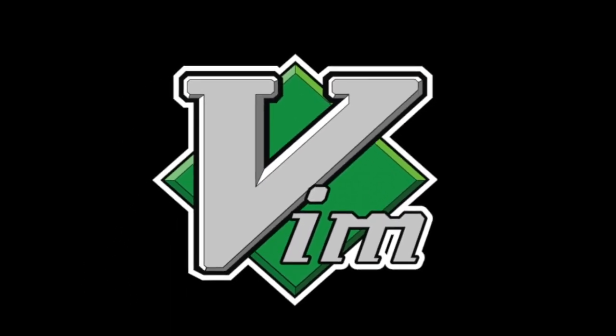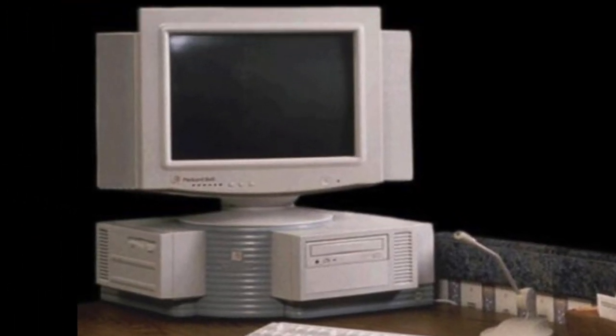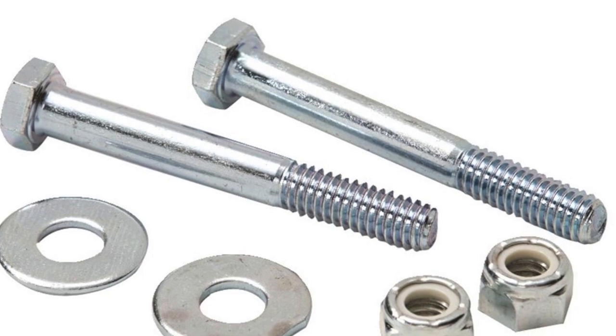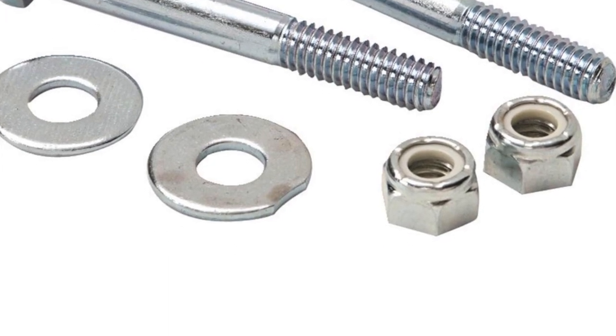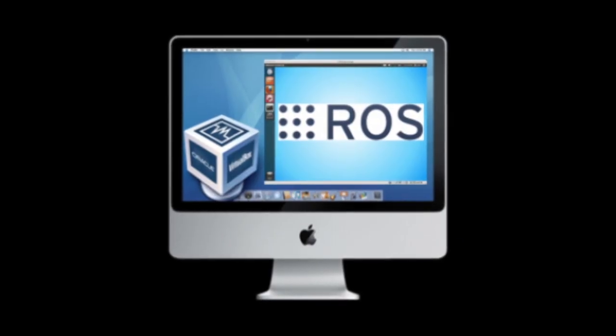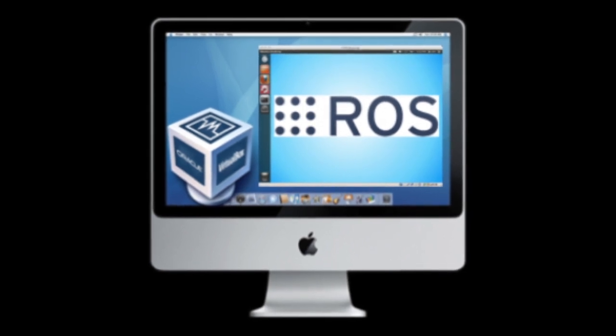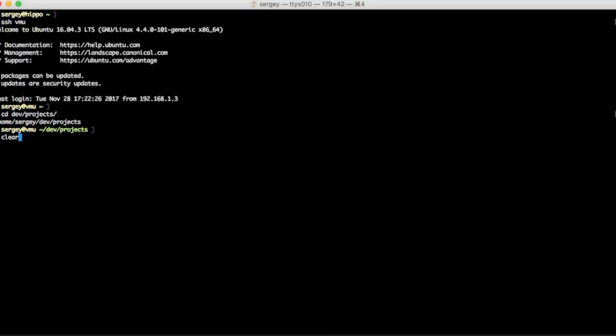editor. I plan to use ROS on Raspberry Pi as a controller. Since Raspberry Pi is short on resources, I chose to develop software on a desktop computer. Once the code is more or less in condition for testing on real hardware, I'll sync the required build artifacts to the Raspberry Pi. At this point, ROS Kinetic is already installed in an Ubuntu 16.04 VirtualBox that runs on my Mac. I SSH into the VM and I'm ready to go.